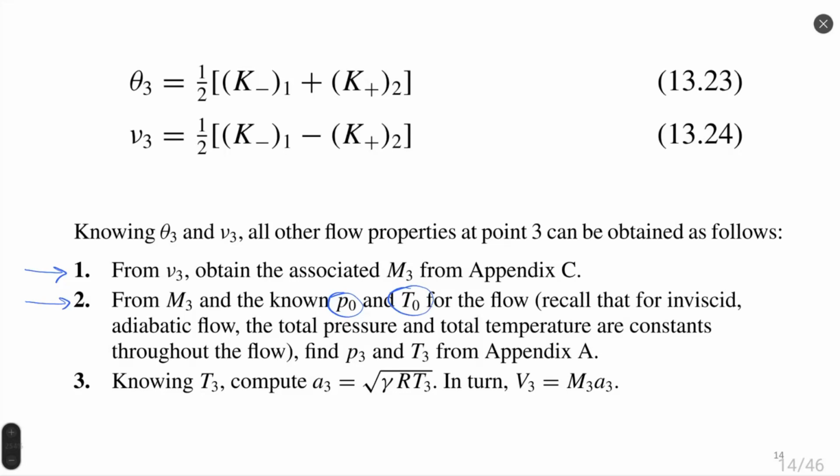Don't forget, the equation of state works at any conditions for compressible, incompressible, viscous, inviscid, isentropic, non-isentropic, absolutely any type of flow. So density is absolutely not a problem when we know pressure and temperature. And we know gas composition, of course. We know gas constant R and gamma.